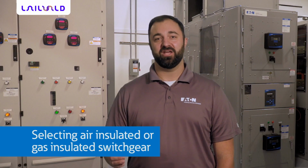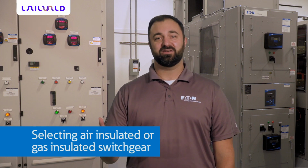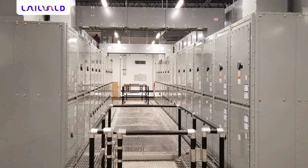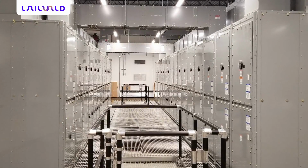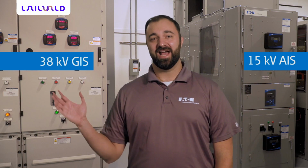In medium voltage applications, selecting between AIS and GIS can be driven objectively by understanding the differences between the equipment. Today, the bulk of installed equipment is air-insulated switchgear, yet gas-insulated switchgear can provide advantages in certain applications. As we'll discuss, one main advantage of GIS is potential footprint savings. In order to determine the right equipment to apply, it is best to understand how the equipment is being designed, operated, and maintained.